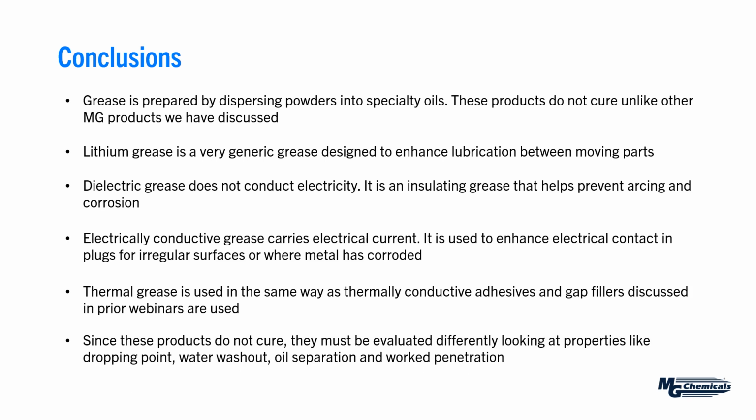So we look at things like the dropping point, the water washout, the oil separation, and the work penetration. That gives us an idea of how well that particular product will fit the environment it's up against, and that's really what a lot of these properties are used for, to help the customer gauge if they have the right product in mind.